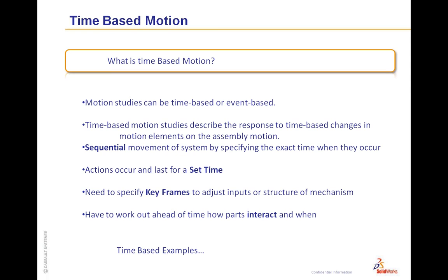But time-based studies describe the response based completely on time. What that requires you to do, it requires you as the user to understand ahead of time how the parts interact. You need to specify the frames in which things are going to change, when a motor actually kicks off, at what point in time.